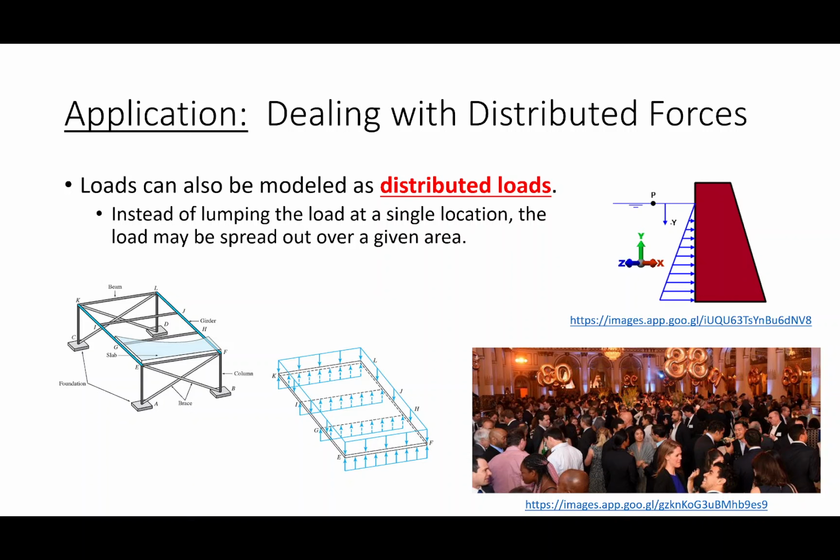But in all seriousness, the loads that we use would be reflective of the use of the structure. To give you maybe an example that's less humorous, we would design rooms, let's say in hospitals. We might design the rooms for 50 pounds per square foot, but we might design the hallways for 80 pounds per square foot or 100 pounds per square foot, because by their very nature, a hallway is going to have a higher concentration of people and stuff in it than a room is. Does that make sense? So you would select the load accordingly.